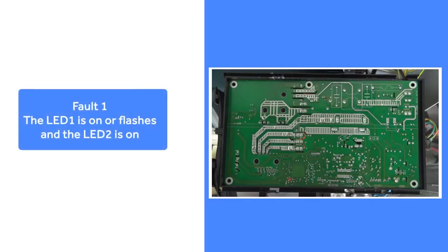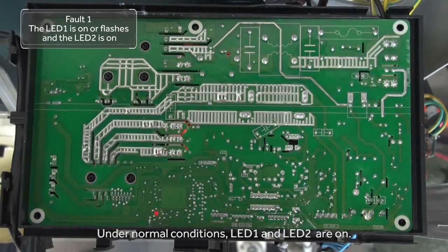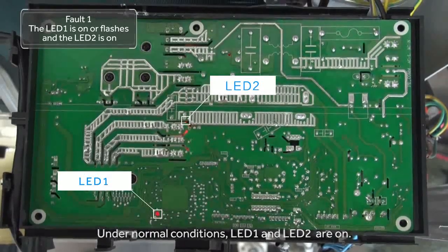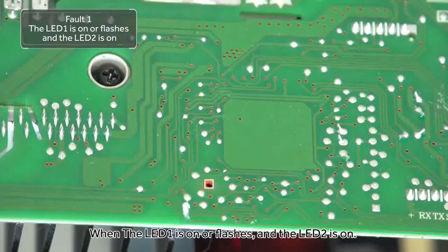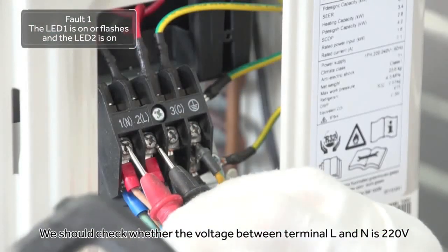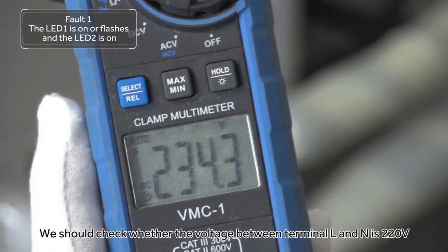Fault 1. The LED 1 is on or flashes and the LED 2 is on. Under normal conditions, LED 1, alarm light, and LED 2, DC 310 volt power supply light, are on. When the LED 1 is on or flashes and the LED 2 is on, we should check whether the voltage between terminal L and N is 220 volt.